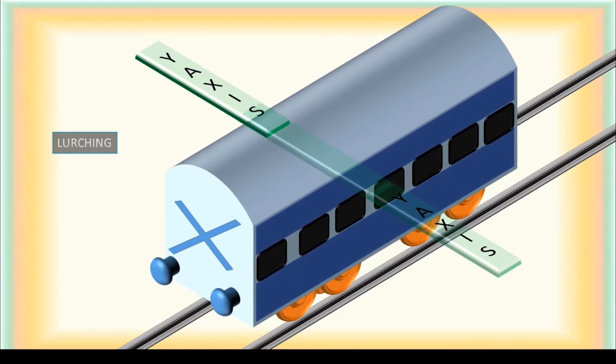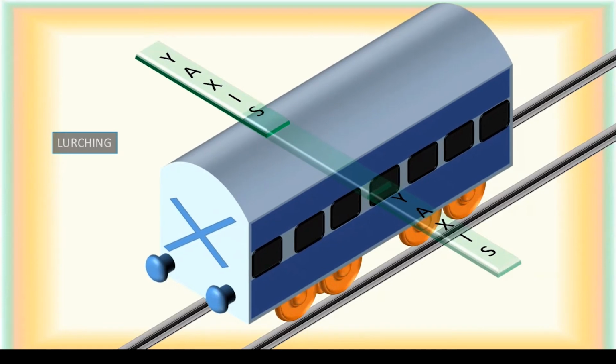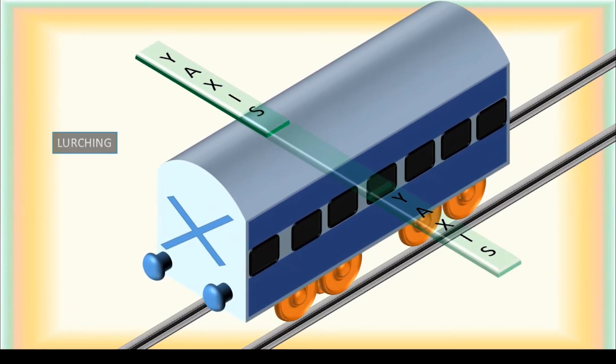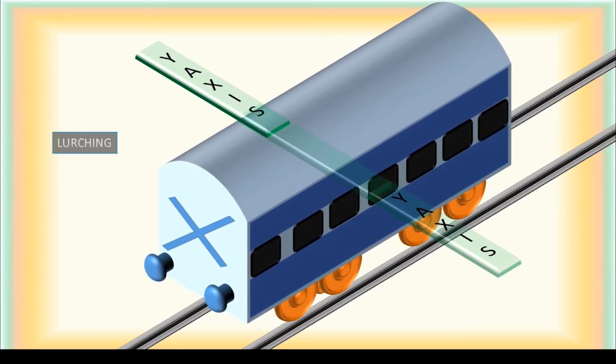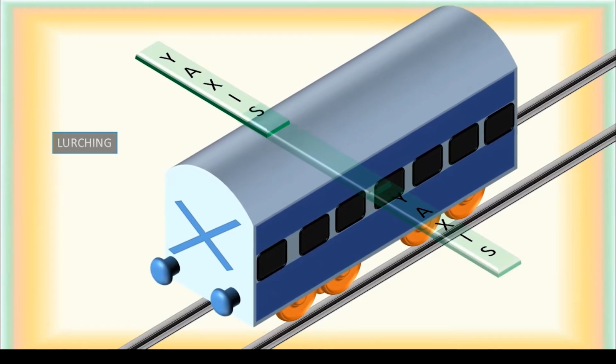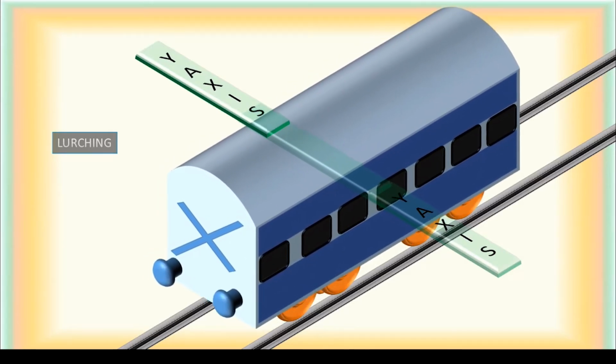Difference in cross level, sir. It will mainly happen due to alignment defect. Track में कोई alignment का problem है तब होगा, ठीक है ना? Number one. Number two, we have designed our rolling stock and track in such a way that the vehicle can oscillate in between. By design only we have allowed it. So these are the two basic reasons for this movement, not due to cross level.